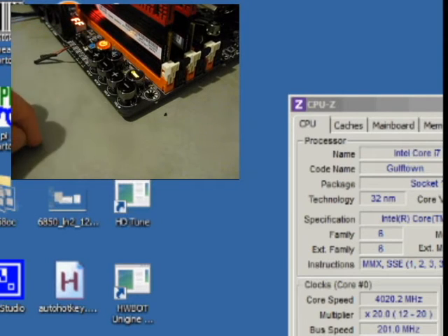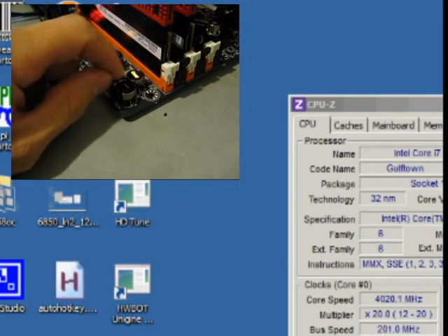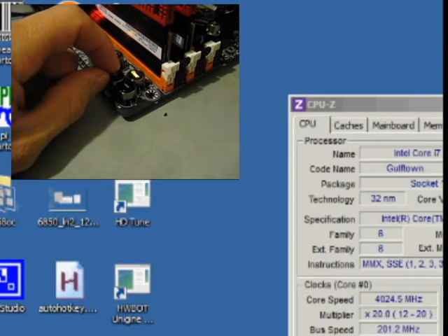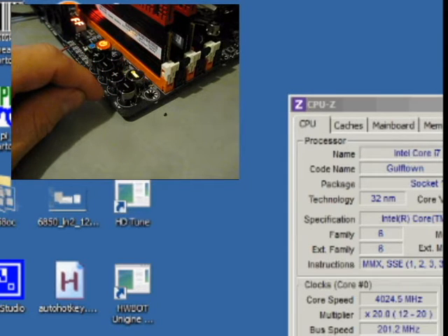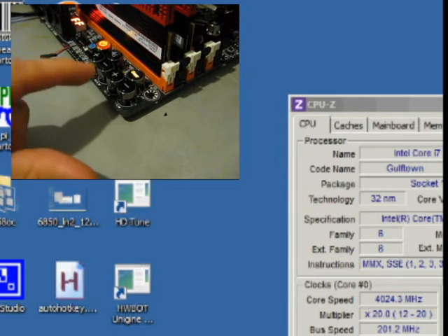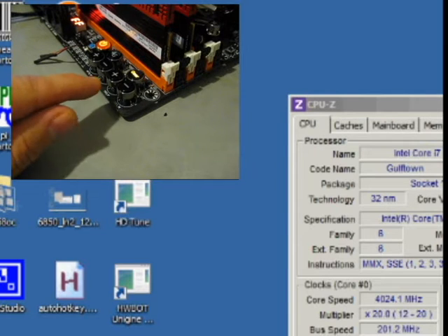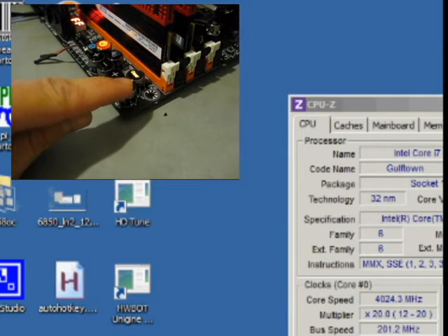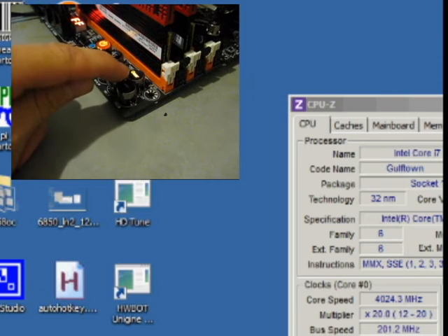if you hit this gear button you can then go in 0.3 megahertz steps, and this might be great for chasing a validation or chasing a high RAM clock or whatever you're after, where maybe you can't go a full 1 megahertz BCLK, but you can go a smaller step. So this is a great feature to lower that in that circumstance.